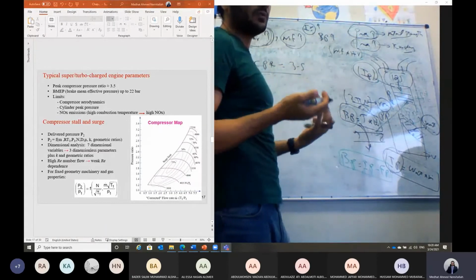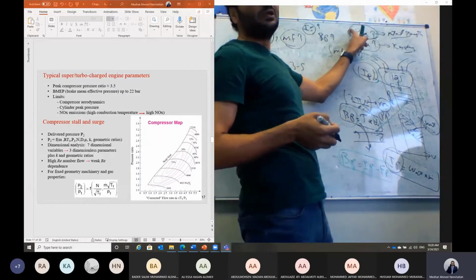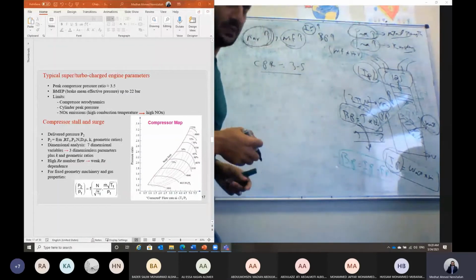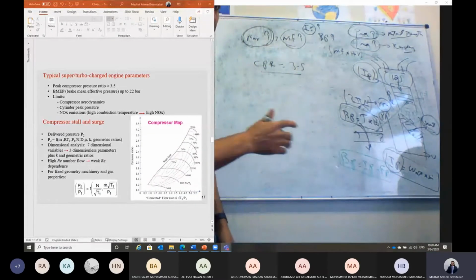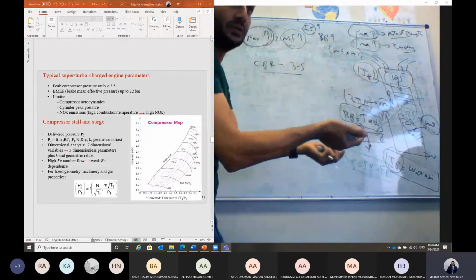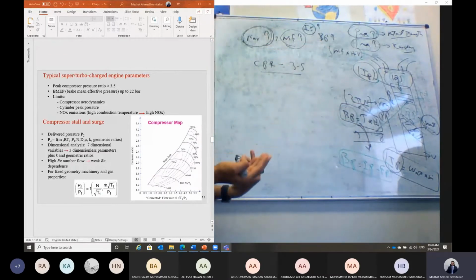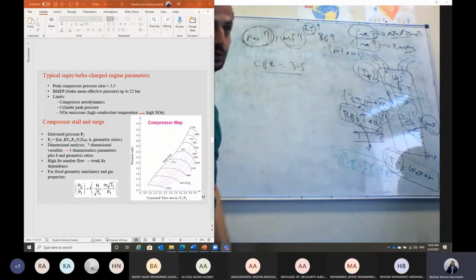So heavy, in this case, we have to use a heavier diesel engine in order to withstand the high pressure generated. And usually, if you are using a turbocharger with a diesel engine, that means this high pressure will be increased more. That means the weight of the engine will be increased, because we have to design the material in order to be able to take this pressure.